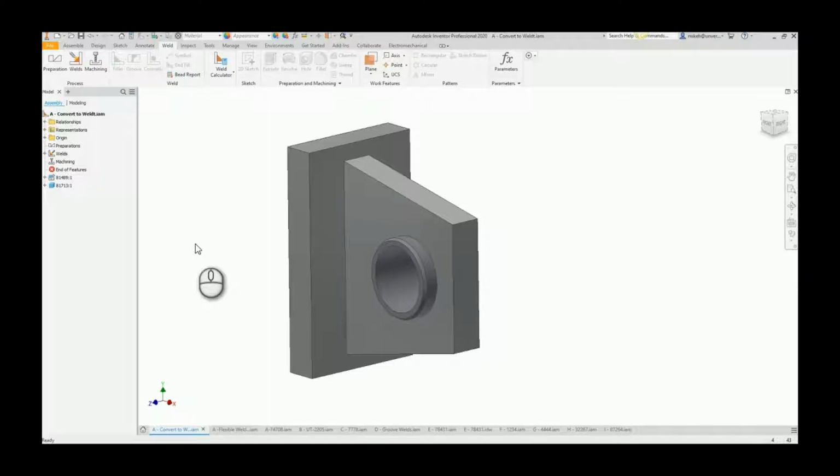And you can also do it if you do need to cut some costs out of a machine and you do have it overly welded, where you can take some welds off and not compromise your design. That can help you determine what kind of percentage time savings is if we would make, say, this a stitch weld, or cut this weld out, cut that weld out. So another very powerful tool.